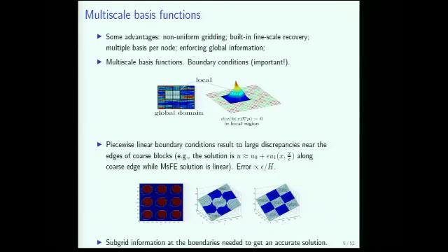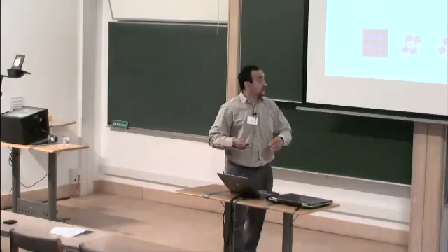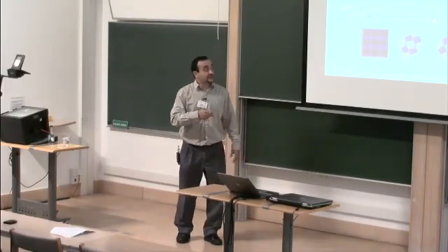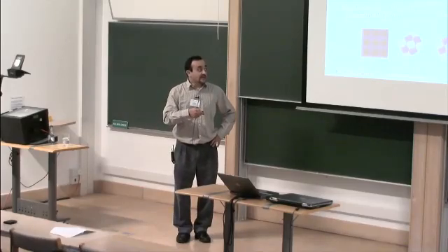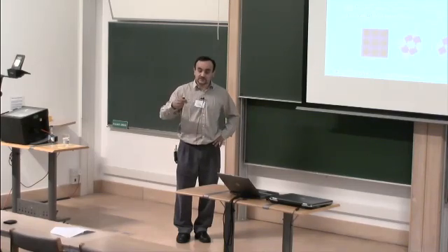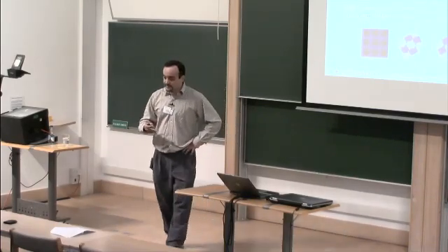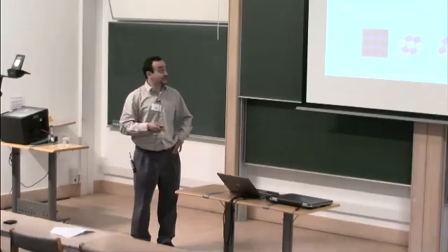And you can see along the edges here, they're not linear. They actually have a very special form. But if I use a basis function, the one that I mentioned before with a linear boundary condition, then the solution along the edge is linear, and that introduces a pollution effect, like Sir talked about. It can give errors of order epsilon over h. So for example, if I have a small scale epsilon and a coarse mesh h, then these errors in a periodic case can go as epsilon divided by h. So it can be very large when the spatial scale becomes comparable to the coarse mesh size.